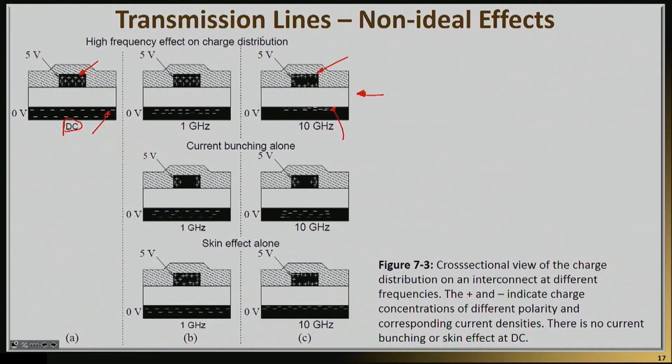So keep that in mind, because a lot of times we forget that, and we fail to realize why loss increases as a function of frequency. And keep in mind, as I mentioned before, that loss is a cause of dispersion too. So you may have taken the best possible dielectric, epsilon r, with a loss tangent of maybe 10 to the negative 4, and still find out that the dispersion is not good enough because of the metallic, the ohmic loss.